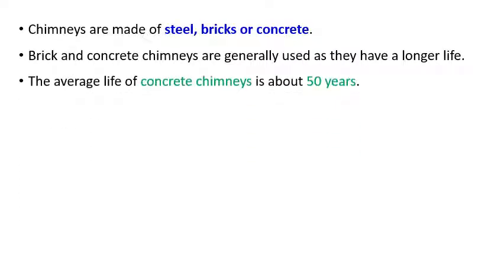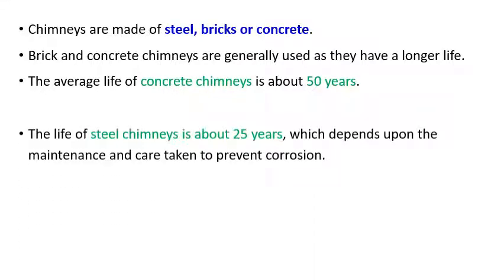The average life of a concrete chimney is about 50 years. Anyhow, it has to be maintained properly. In steel work we can make a patch-up, but if brickwork is there, we have to do masonry work during the annual shutdown.